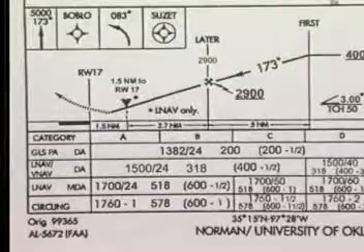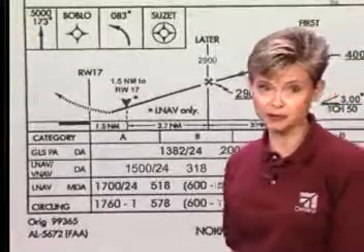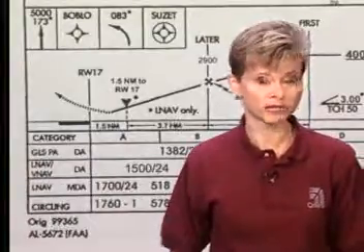Generally, the area covered by the TAAs for an approach includes one or more airways, so you don't need feeder routes. But if all the airways lie outside the TAAs, the chart will include feeders aligned with the appropriate IAFs of the T. Now that we understand how to get started on this approach, let's drop down to the minimum section to see how low we can go.